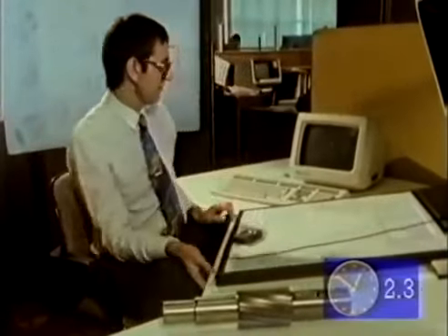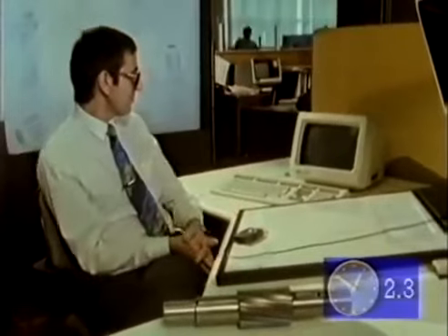The system is asked to measure particular points on the drawing. Because dimensional information is always put into the drafting system as actual sizes, that is effectively at a scale of 1:1, the system can calculate true dimensions from the coordinate information directly and add the dimensional annotation automatically to BS308. So it's taken Alan about 6.5 minutes to create this drawing.